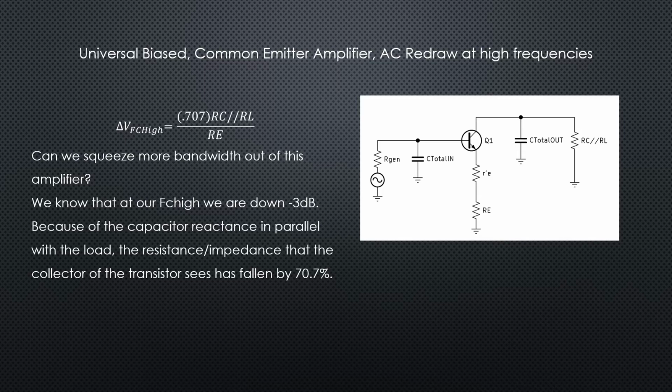So is there a way for us to bump that gain back up? I mean, we know that that capacitor in parallel with the load is going to just keep sucking that number down as frequency goes up. So what can we do to prevent that, or extend our bandwidth by extending our frequency high cutoff?